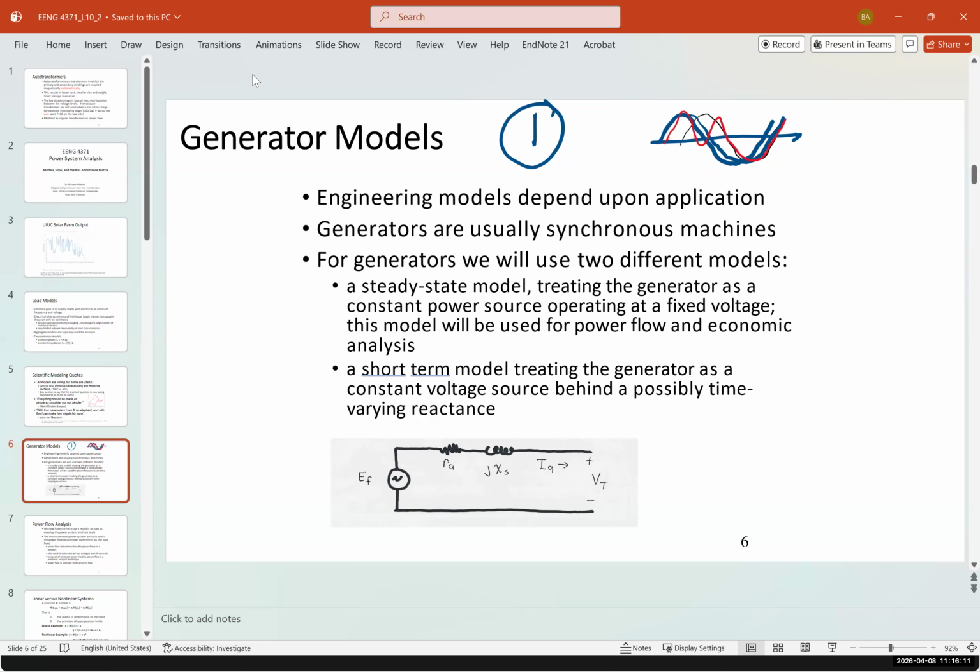Yes. Once you have your generator locked in with the grid frequency, does it naturally want to stay there, or do you have to constantly be? So the good thing about the grid is that the grid itself has a little bit of cushion. It acts like it stores a little bit of energy in the system. So if you flip a switch now in your house, the generator would run a little bit higher. It could absorb a little bit of load, but if it's a huge load,